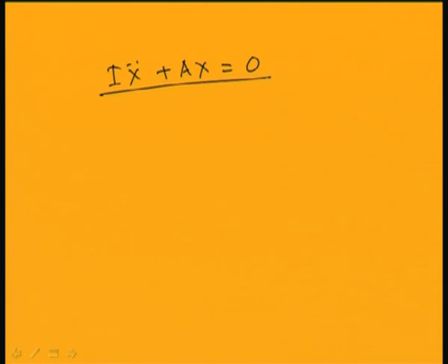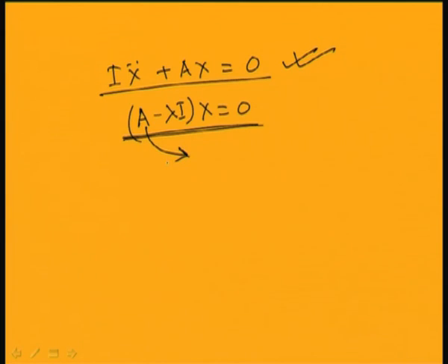Assuming the normal mode x equal to X sin omega t, this equation reduces to the form (A minus lambda I) X equal to 0. This gives the eigenvalues, and the eigenvectors corresponding to the eigenvalues are the normal modes of the system. So, for an nth degree of freedom system you have n eigenvalues, and corresponding to them n normal mode frequencies and n modal vectors.